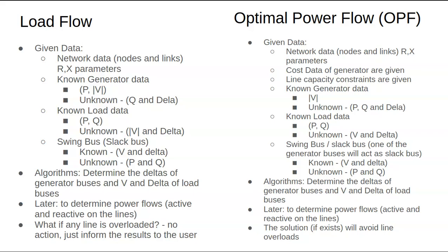Now I look at both the generators. The first one is like a diesel generator, and the second one maybe some other fuel, some kind of lesser cost fuel. So you will say, okay, first let me use that one and then this one. People used to simply do it like that, but now if you want to really do it mathematically, you do this OPF. Here you know P and Q, and you don't know the peak, and you know how much voltage you want to maintain. I want to maintain this much voltage, one per unit. Then let the program run and tell you, okay, at 10 o'clock, this much should be generated here, this much should be generated here, to meet the demand.